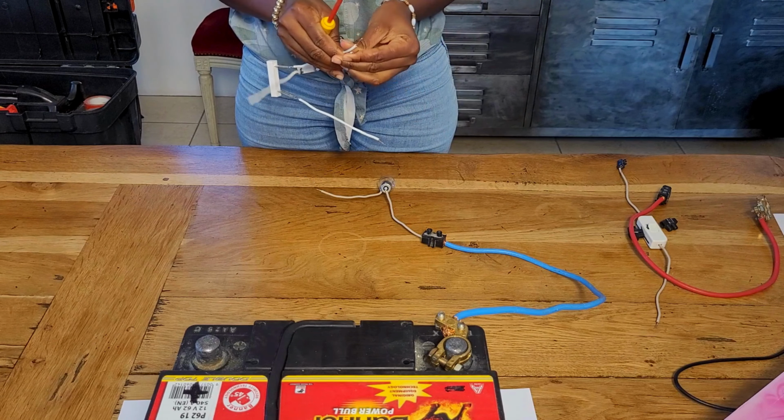And when we come to this ammeter, there are two types. There is the multimeter and the analogic ammeter. Important notice, red cable in 10 amp hole and then the black in the COM hole. And the symbol for ammeter is an A. Measuring circuit scheme. Note, measuring intensity is performed inside the circuit.